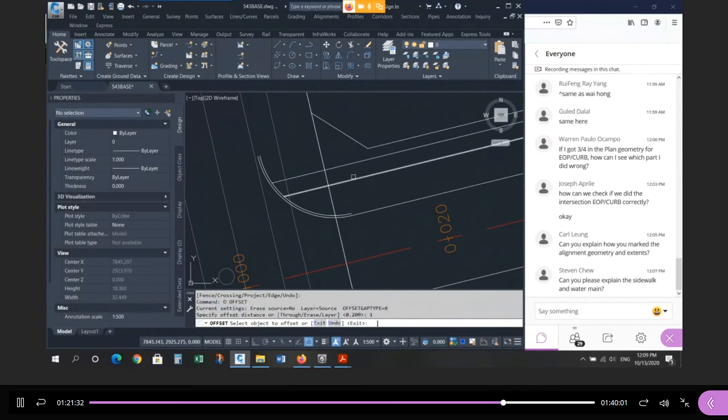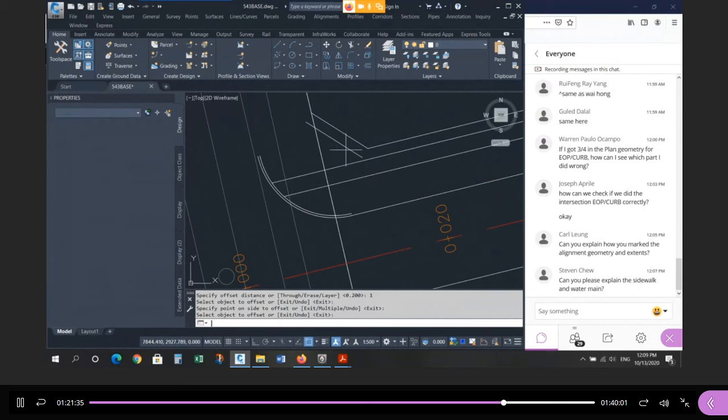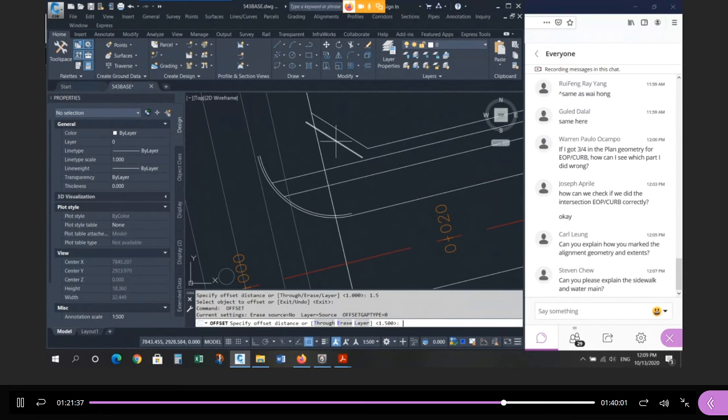They did that. Some people did offset of 1 meter here with a 1.5 meter wide. And then you have a fillet of 0 between these two. Some people drew this for the sidewalk. That doesn't make any sense. It doesn't go anywhere. You want to take it to the asphalt. Right? You want to walk along the sidewalk, and then when you get to the concrete curb and gutter, step down onto the asphalt and cross the street.